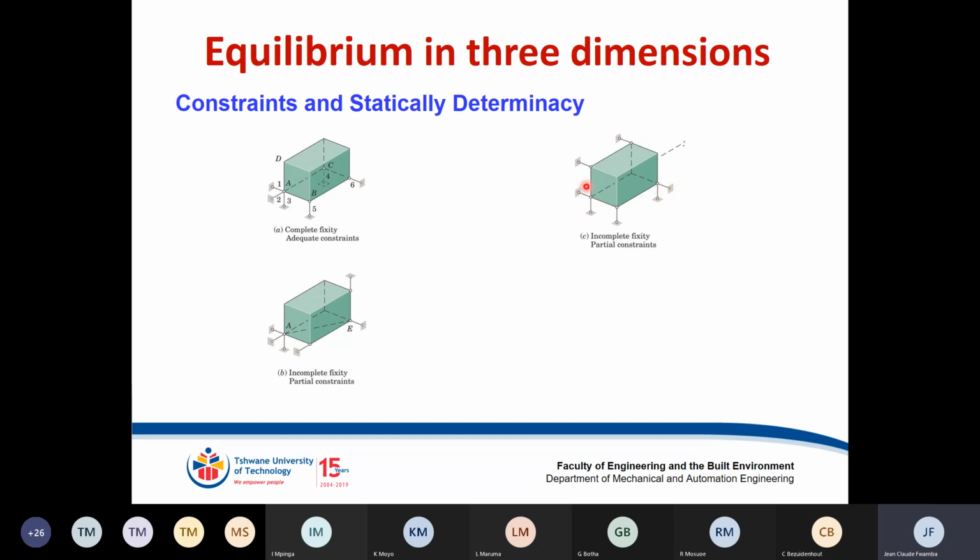On the y-axis, I've got 4, a little bit on top, or kind of overdid it, but they are there. But on the x-axis, there is nothing, no restriction, which becomes a problem. So your system is partially constrained. Number 4, the issue is member 7, or restriction number 7. That's where you are overdoing it, right?